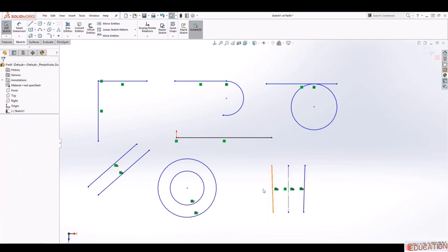So in order to make two objects symmetric to each other, you need a center line, and your center line has to be a construction line or center line. And that is pretty much relations in SolidWorks, and you will learn the relations as you go, so don't worry about knowing all the relations now, I'm just showing you the overview of it.